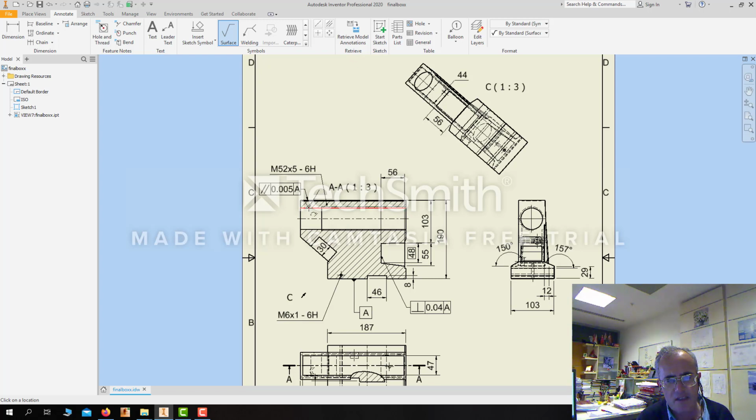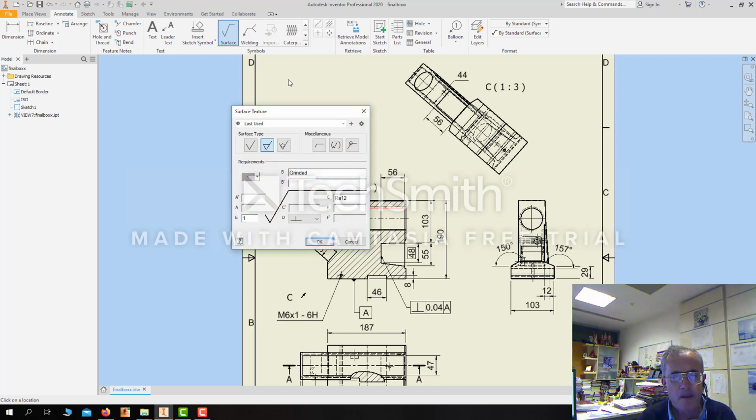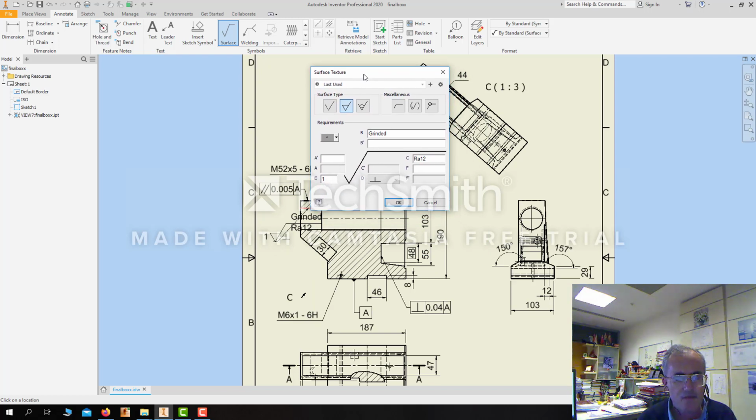Find the surface limit line, okay, and then with a click along the surface limit line at a point indicated, and then move the cursor away. Find a suitable empty space in the vicinity to anchor the symbol. See that approximately the distance between the outermost boundary of the projection and the cursor or the symbol is 10 millimeters, and then with a click anchor it. Right click the mouse and then say continue. Click on the Continue button. Then the dialog box to fill in, to make the selections, will appear on the screen.